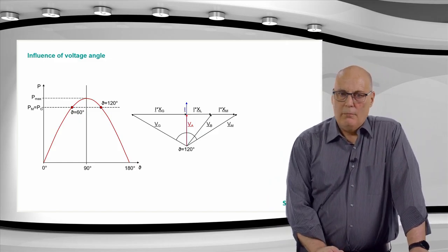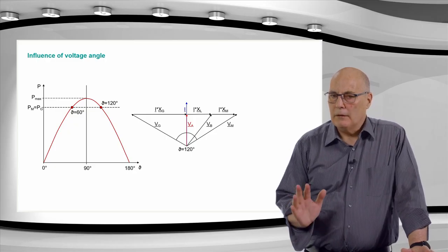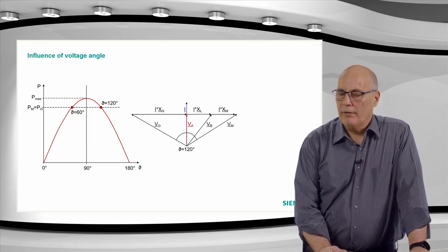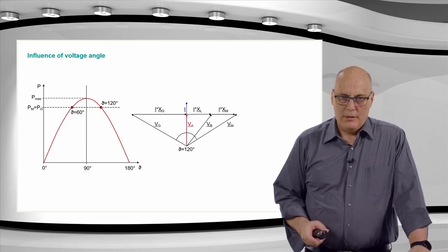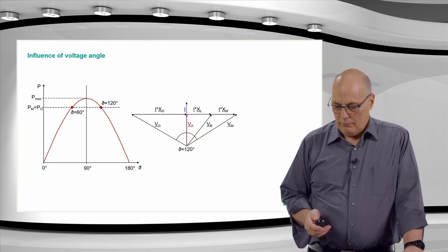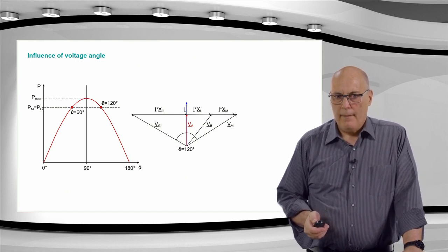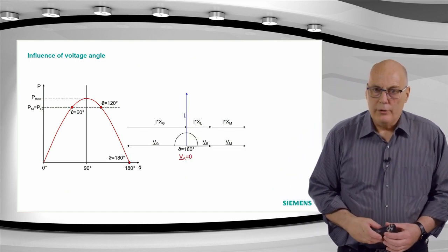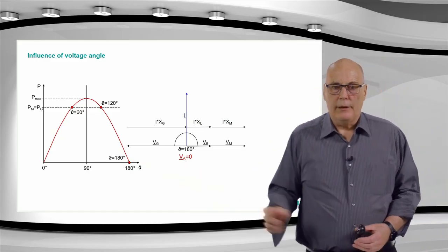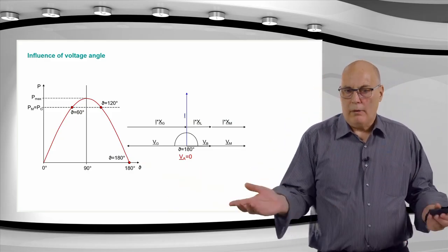But for the power swing blocking, it is interesting to know, but it is not of any significance in terms of settings or anything like that. It's just parameters one should know about. Another interesting point is 180 degrees down here. It's the so-called out of step point.